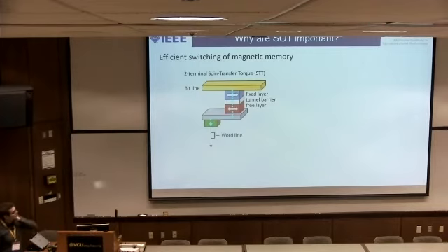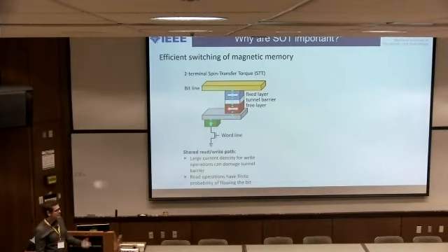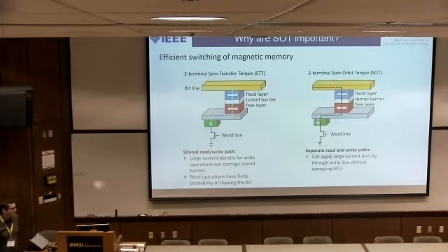If we go back to our MRAM picture, here's our tunnel junction. Of course, what we usually think of as a two-terminal device, you pulse a large current through this device to switch this free layer. Of course, over time, these are really large current densities, and you can damage that tunnel barrier, for example. And so there's some interest to go into what we call three-terminal devices, which is shown here.